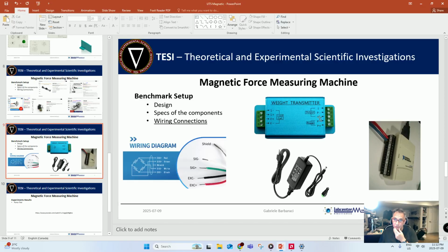The output, the V, goes into the red wire in the DAC system, while the P minus, the lower voltage, goes in the blue wire. The DAC is configured in differential mode, not ground, or RSE, reference single-ended.